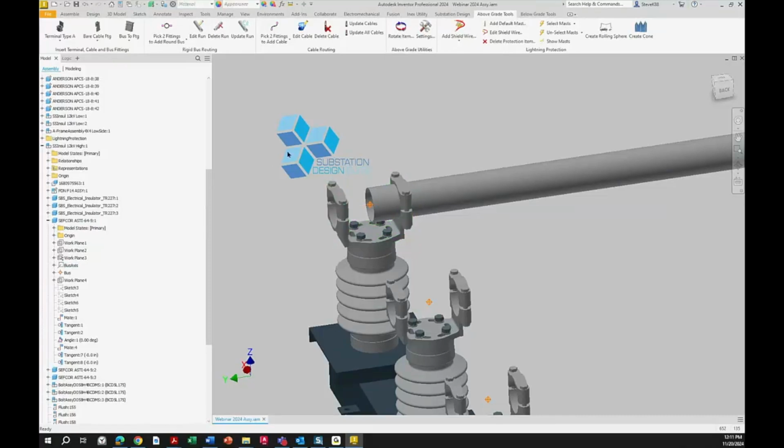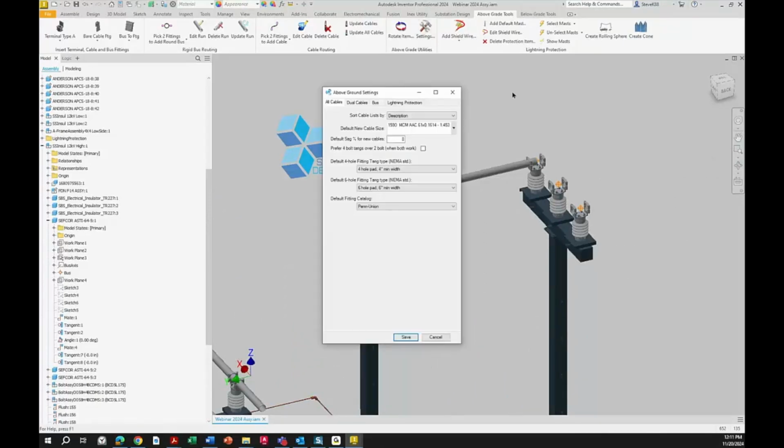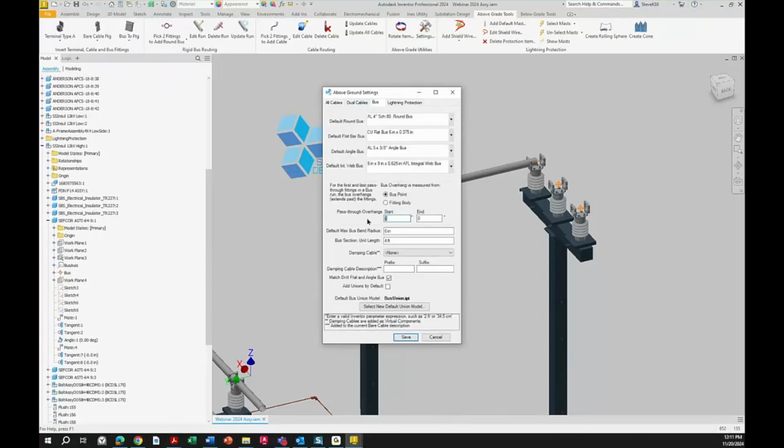And when we do an offset to that, that is when we get into how far beyond that work point it goes. So if we put an offset in here, 12, we want units. It doesn't have to be inches. It could be 12 meters if you wanted, centimeters, whatever you want. I'm going to stick with inches today because I'm used to it. And I'm going to have the same number on both sides.